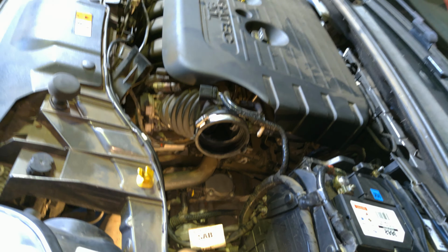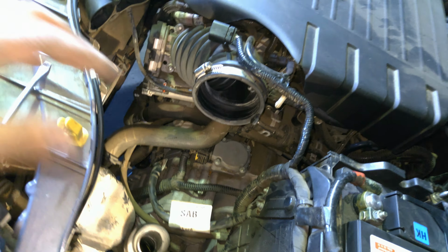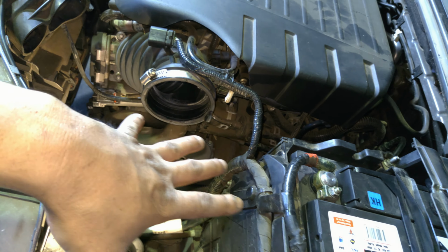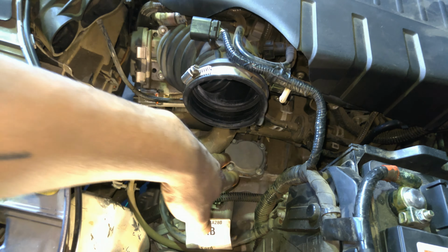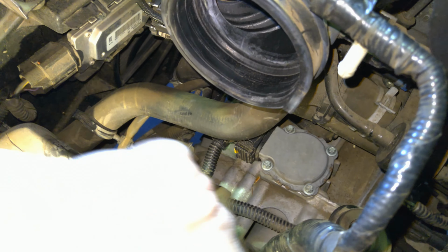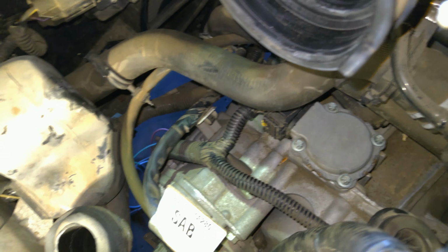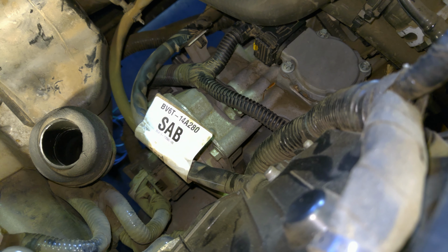Alright, the top actuator for this car is sitting right in this area here. There's your air filter. You've got to pull the air filter and a few covers off. You can get to this actuator right here. That's your second clutch actuator. Alright, they're both identical. The bottom and the top one, both identical. Same exact plug and everything.